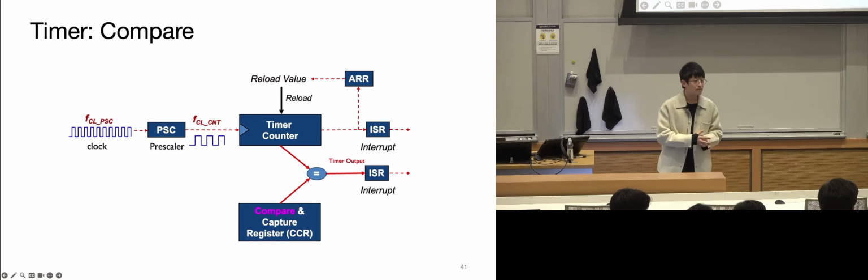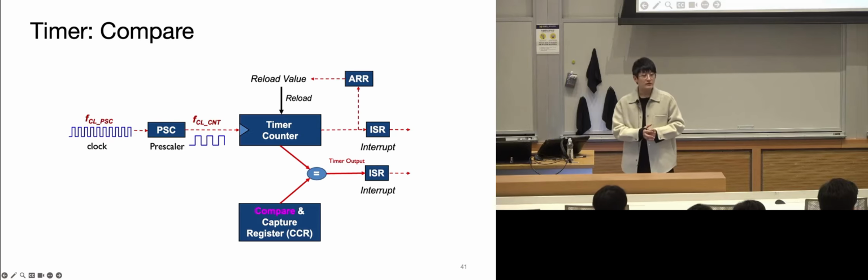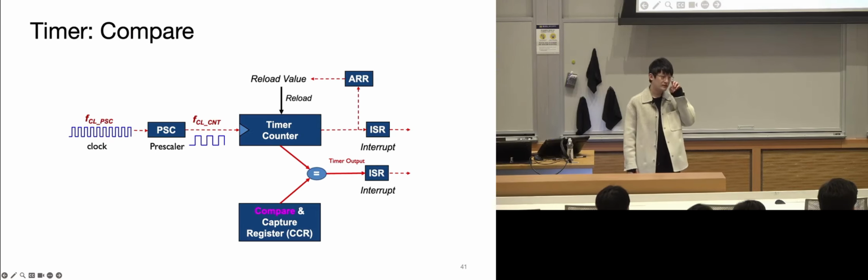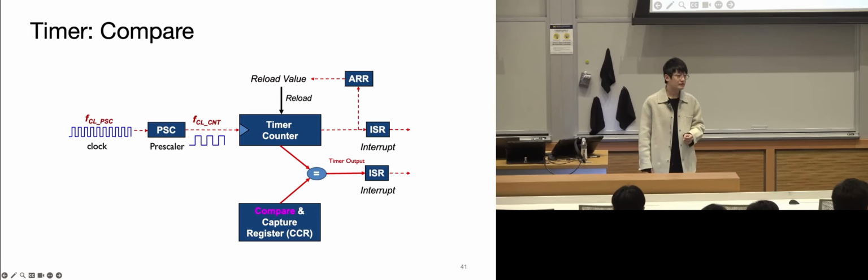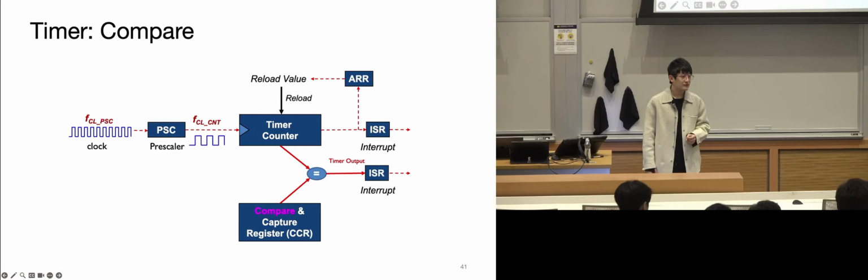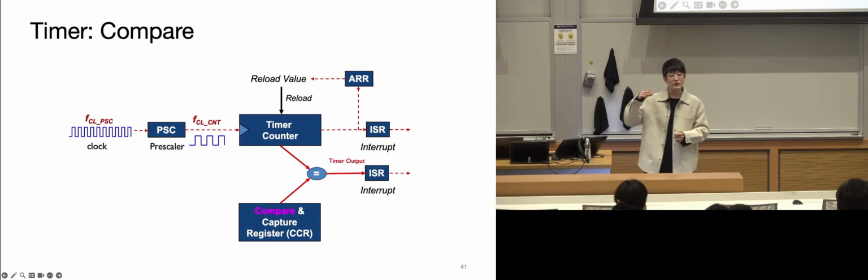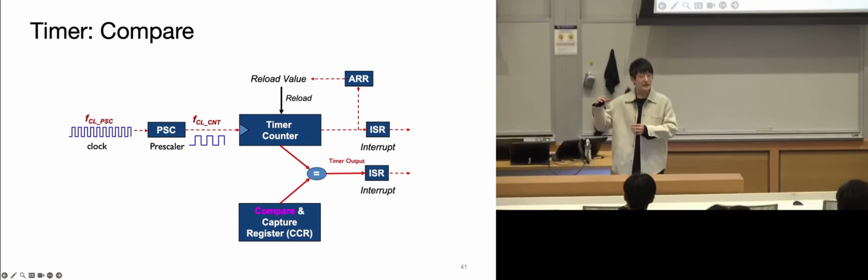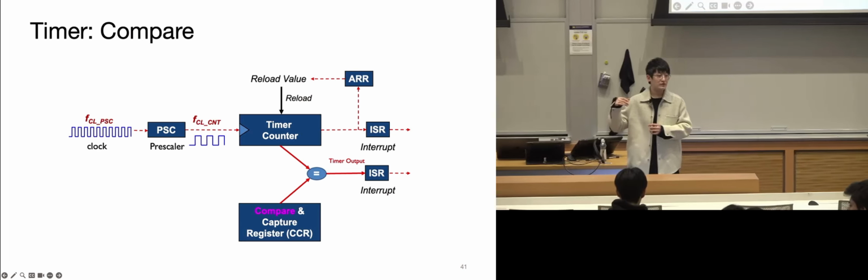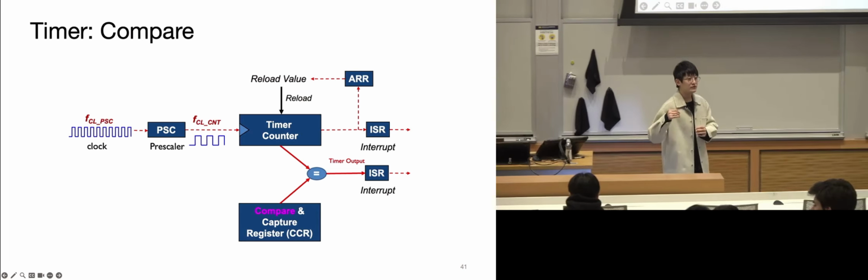So the output compare register enable is for the output, yes. Right. The interrupt wouldn't be doing anything in that case, right? I could only see the interrupt being used for the event queue and other stuff, not on the PWM. The interrupt will control whether to set the output pin to 1 or 0.